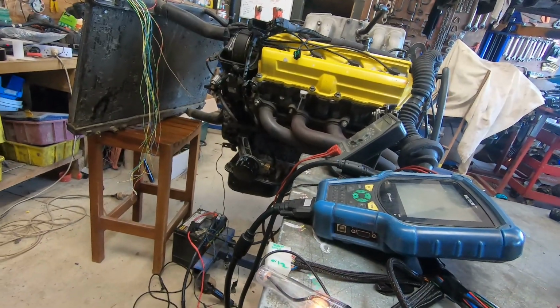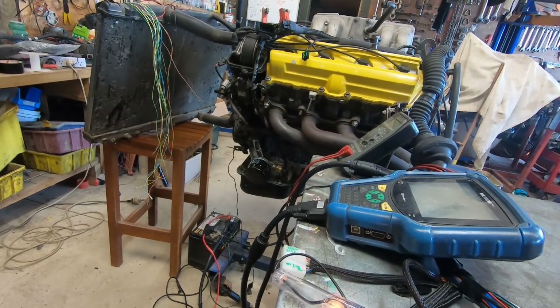So I've got an engine here that if I hit it on the starter, it just starts and stops. If I feed it engine start, it runs. So how do I diagnose this? And of course, if I'm putting fuel in and it runs, it must have ignition. That's not the case, because Toyota played this trick on you and put fail-safe or limp mode in place that turns the engine off on an LS400 ECU and not a Soarer ECU, just to really make it fun.